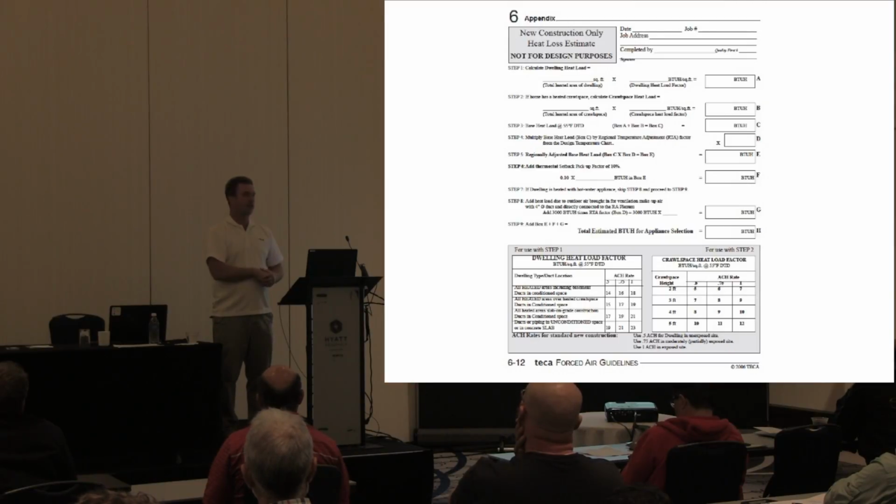And even if they still have forced air heat in that room, they have a separate thermostat on the wall where they can boost it up a little bit with some floor heat or whatever, as opposed to anything else. But it's a lot easier to zone because with the variable speed pump, it doesn't really care. It'll scream through the pipe a little bit, but nobody hears that, so nobody complains about the noise screaming through a water pipe. Whereas they're going to scream.